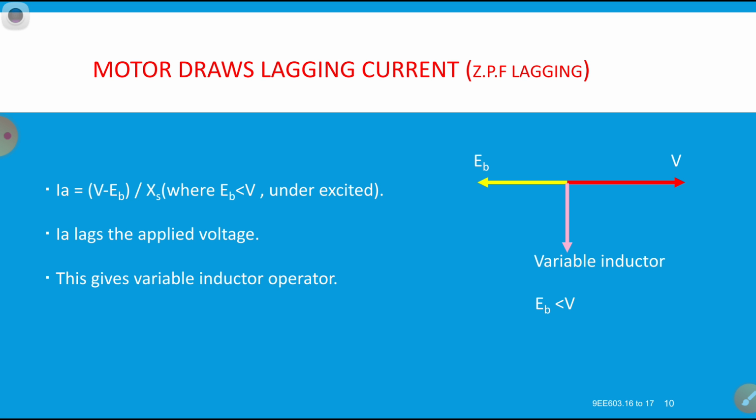Now what to do? We used the OLTC, we switched off the capacitor banks. Even then the receiving voltage is more than the sending voltage. How to compensate it? Otherwise there is a high voltage at the receiving end side, and the consumers may object.